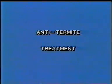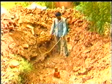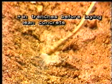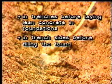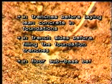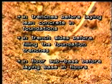Anti-termite treatment. To save wooden joinery from termite attack, anti-termite treatment is carried out in 3 stages. In trenches, before laying lean concrete in foundations, in trench sides before filling the foundation trenches, in floor subbase before laying base concrete in floors.